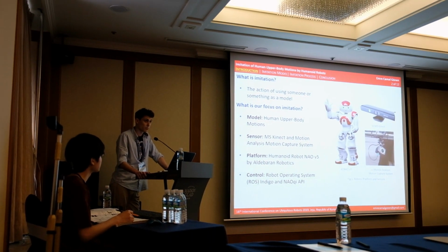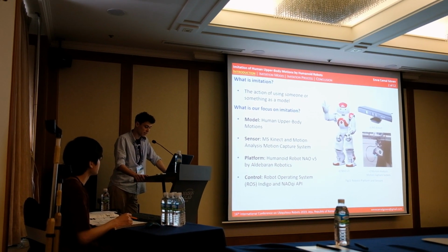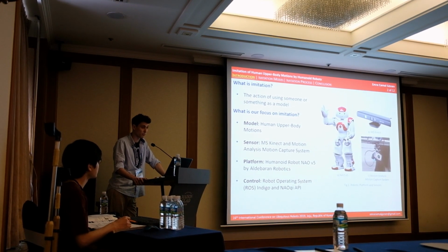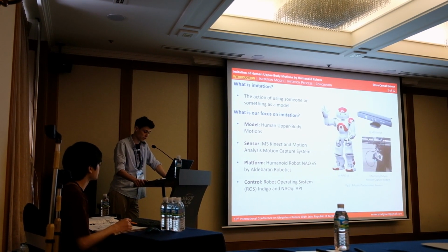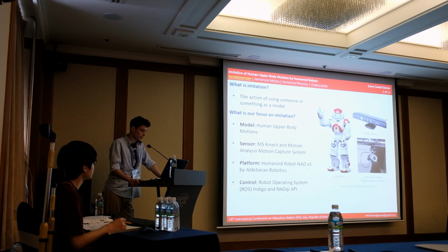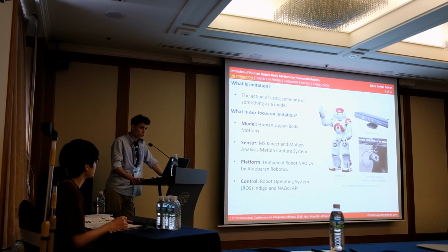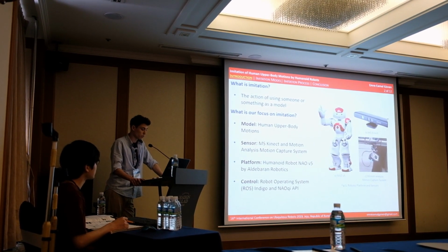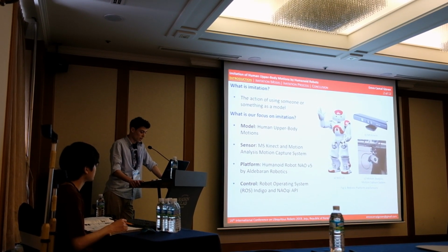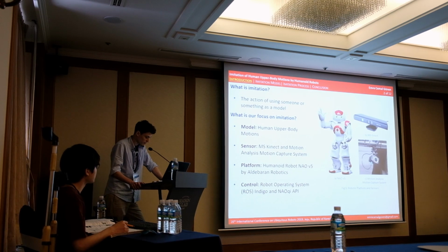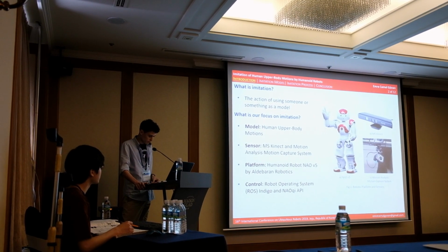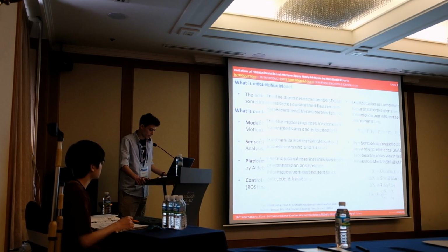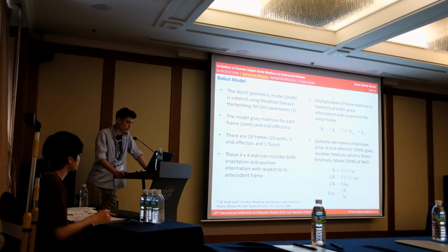One is markerless motion, Microsoft Kinect, and the other is marker-based motion analysis motion capture system. After tracking data with sensors, we made all calculations using Python programming language and controlled the robot using ROS Indigo and NAOqi API. Now let me explain the whole process.